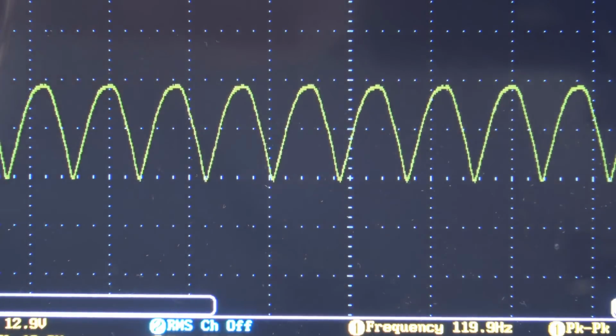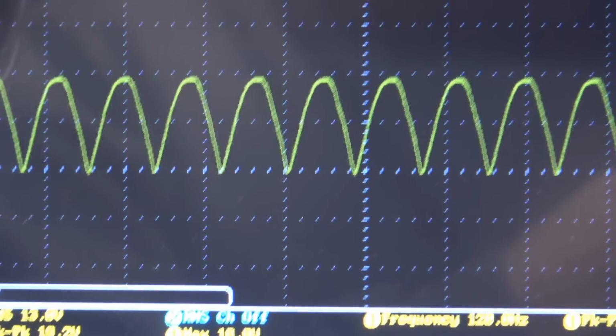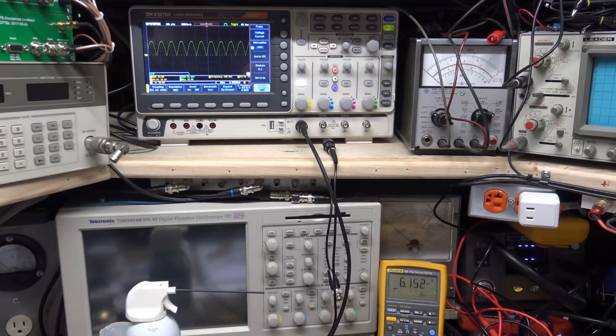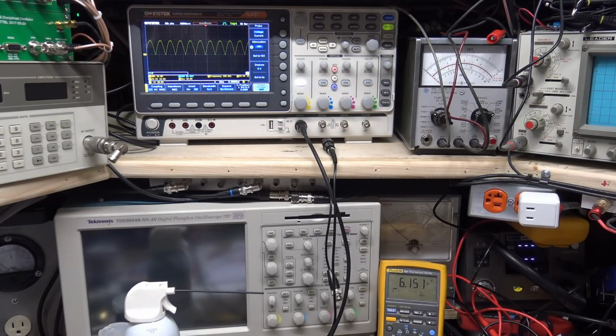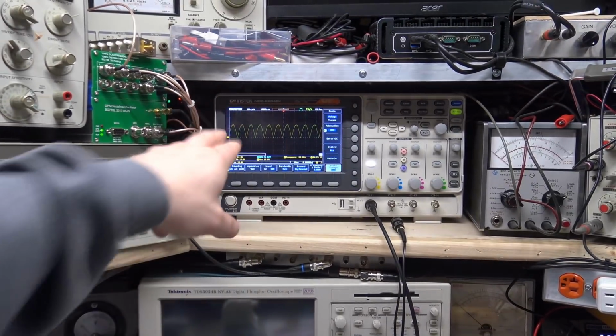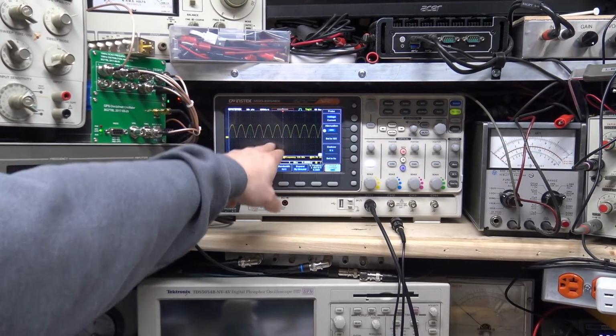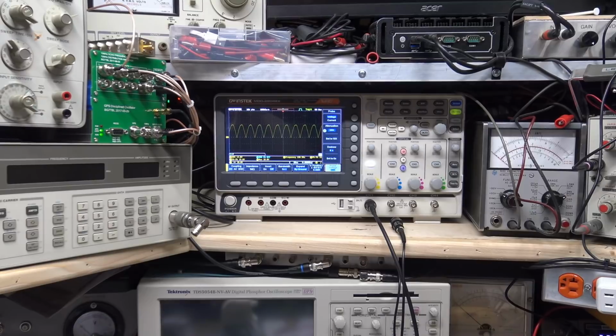Anyway, I just wanted to go over a little bit more about RMS, about an offset waveform, and about how those things are calculated by your test equipment. You can see how if you don't understand how your test equipment works, it can throw you off. So just remember, your meter will always take the offset out of the signal, unless you have a meter that's capable of taking that into account. And your oscilloscope, when you're using the measurements, it will actually measure the true peak of the waveform and give you the RMS value based on that. So I hope that makes sense.